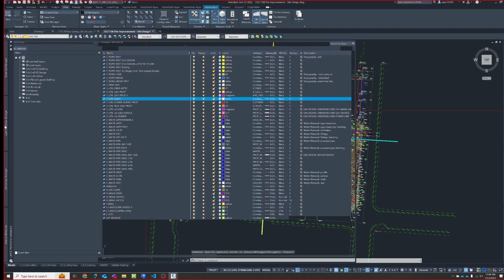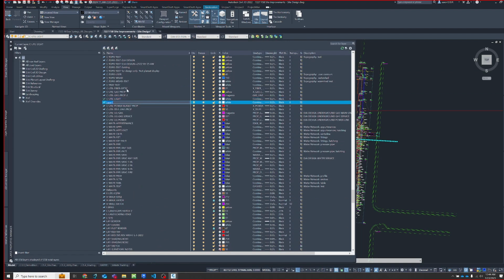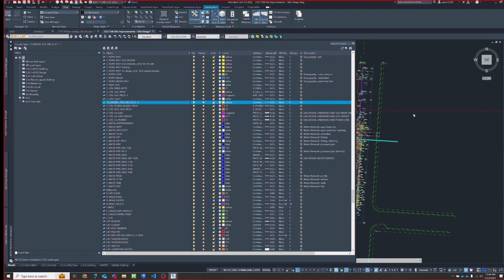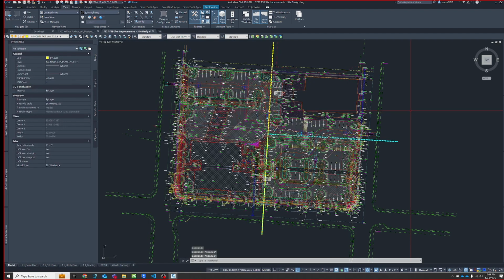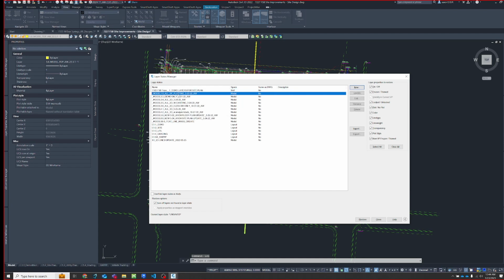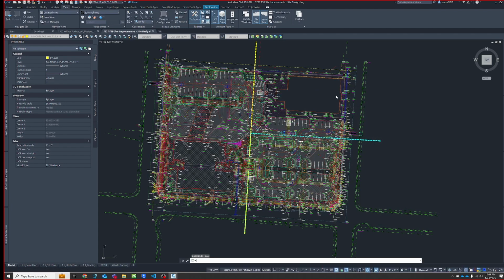Let's say I made a new layer right now. I'm just going to call it whatever. And let's give it a color. And I made a line here. It can be something difficult to manage with them. And you can turn this setting to the opposite so they always show. I tend to leave them always off so I don't like to be surprised as much on the other settings. So let's say I go back to this layer state here, my default one, it should turn off that line I just made. So if there's new layers that come into your model, just keep that in mind.